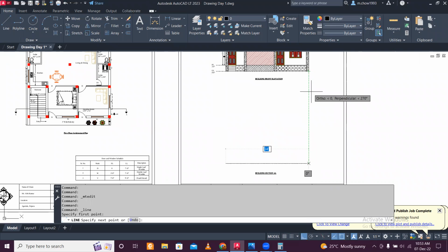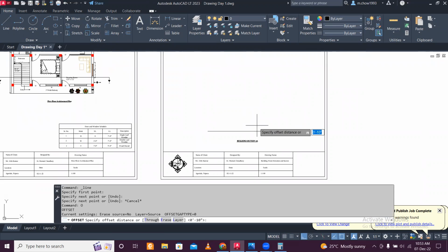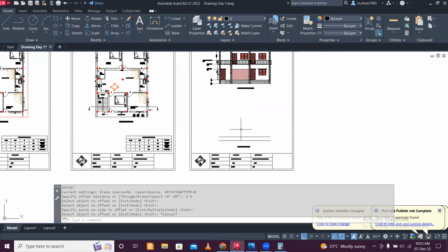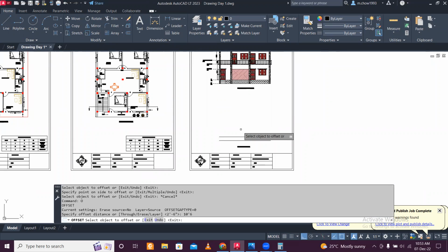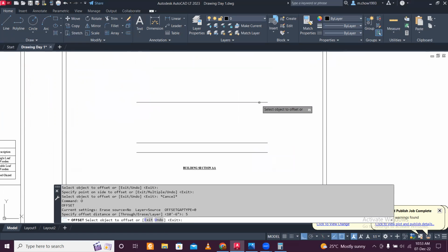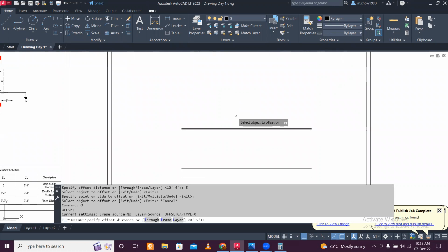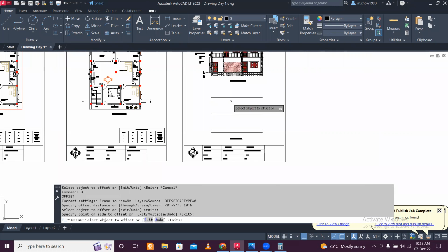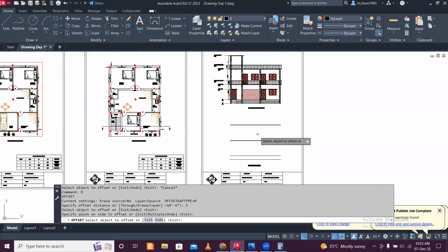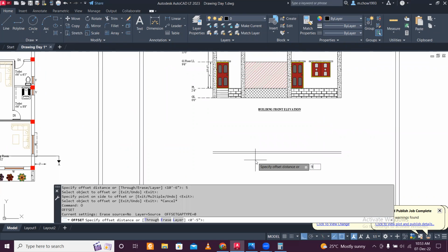This is a very useful feature where you can take this thing. The plinth height, you can see, is 2 feet 6 inches. So let's go 2 feet 6 inches. And then it is 10 feet 6 inches. And then it's a 5-inch slab, so the slab will obviously appear here, a 5-inch slab below. And then we have another 10 feet 6 inches. That will also appear, and a 5-inch slab here for this. And this is a 9 feet staircase, that will also appear, 9 feet.